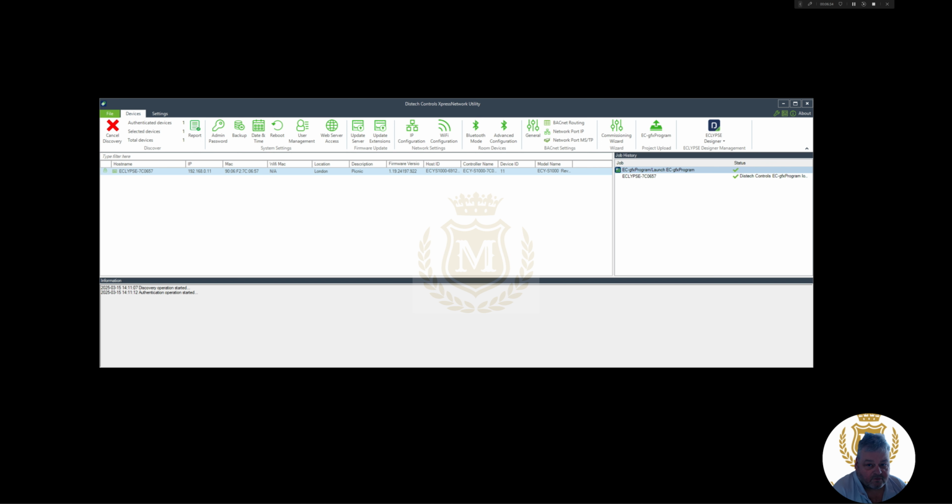And I can bring that across and show you that someone's had to write the software in the controller, and the controller's got the Modbus connection to the meters, and every meter is being brought in, and every point of every meter is being brought in, and then a description has been made for each meter. And then once I've brought it all into the supervisor via BACnet connected to the meter, I've then got to put them into the individual folders like I have done.